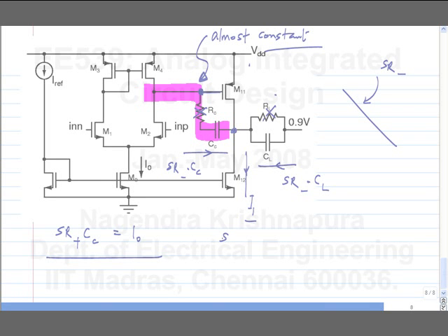and what about this other condition here? This is a fixed current, right? Unlike M11's current, which was changing in response to the gate source voltage, and the gate source voltage responds to the input. You can pump more current through this, but the amount of current that can be drawn out is, the maximum is I1. The best case is when M11 is completely cut off. Right? When M11 is cut off, a total current of I1 can flow through CL and CC. Is this okay?